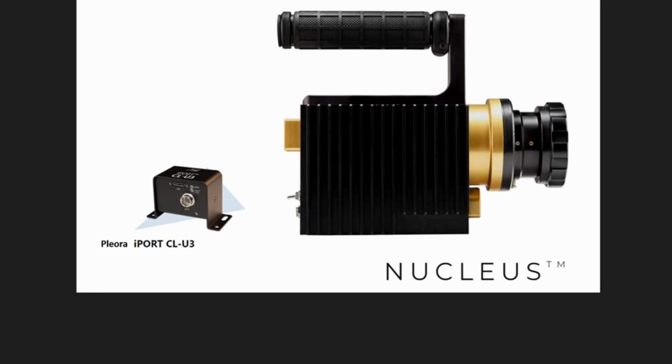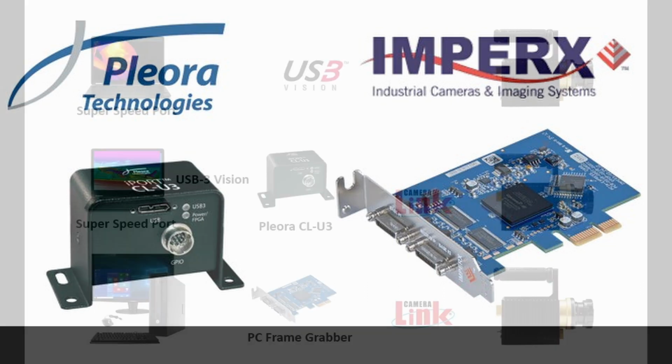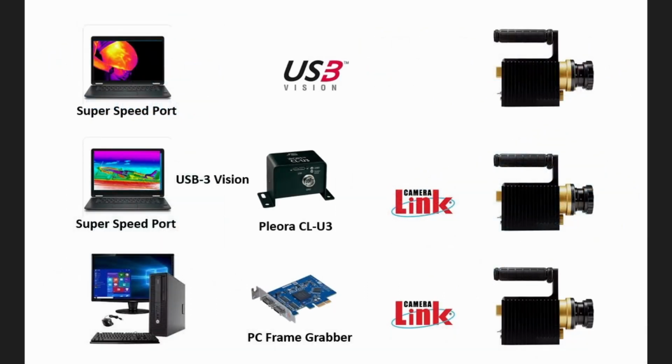The Camera Link interface is used in conjunction with a third-party frame grabber, and the camera delivers 16-bit gain and offset corrected, dead pixel replaced data to the frame grabber, and all of the range compression, snapshot capture and sequence captures are managed by the third-party frame grabber.